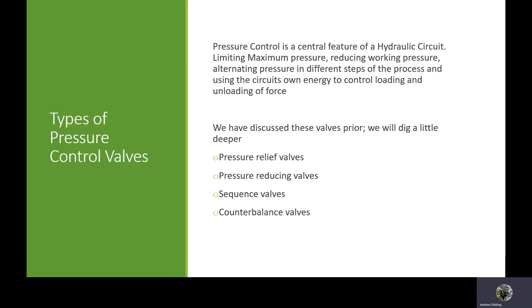Okay, now we're going to talk in this presentation about pressure control, and that's a central feature of any hydraulic circuit. You want to be able to limit your maximum pressure for safety reasons, reduce the working pressure so you don't use any more energy than necessary. You may want to alternate pressure in different steps of a process.